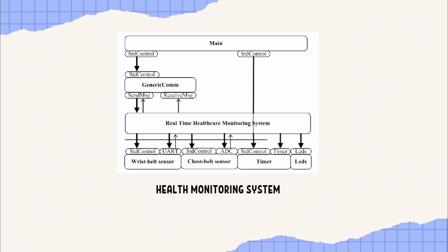In a TinyOS-based application, developers may integrate ADC functionality through appropriate components, drivers, or interfaces that allow the system to interact with ADC hardware. These components or interfaces enable the reading of analog signals from sensors, convert them into digital values using the ADC, and then process this digital data as required for the specific application.